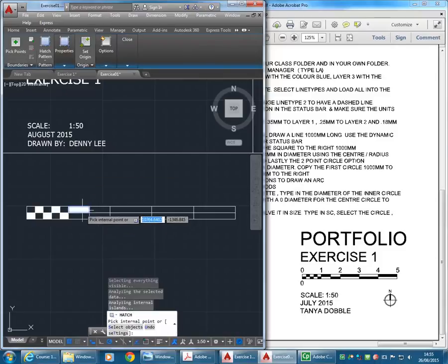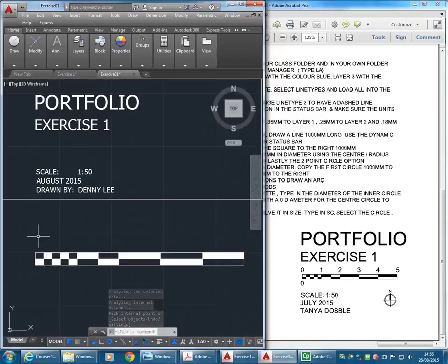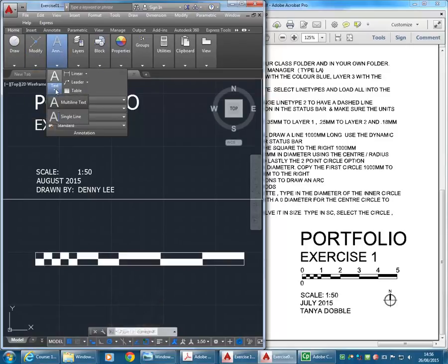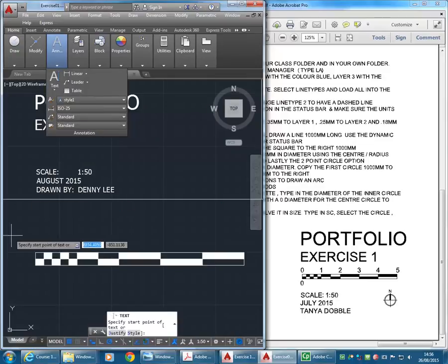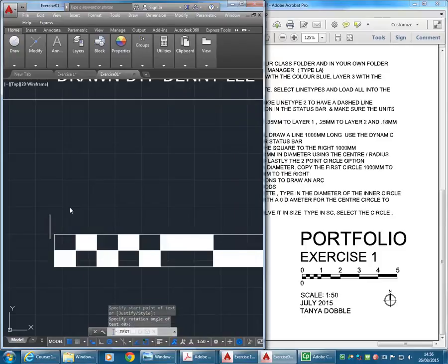So once you do something like this, you should be able to reuse it on all your drawings. So it's good to do it properly, and then again you can just use normal text, and here single line text instead of multi-line text would probably work better. So starting there, it'll ask for the rotation angle, so I'm going to press enter to keep it at 0 and then type in 0 for the actual text.